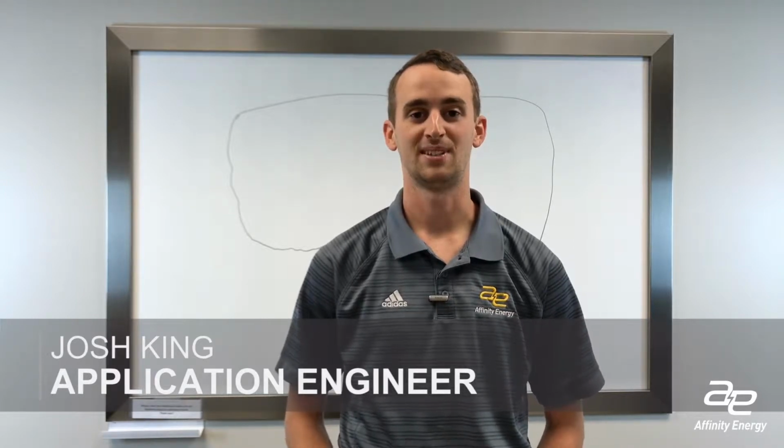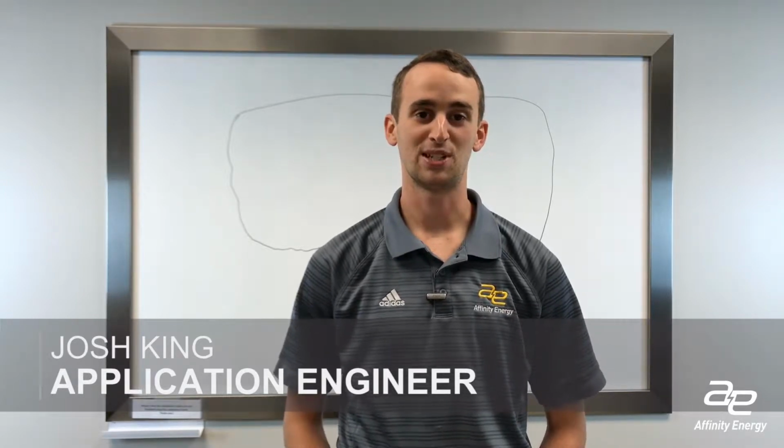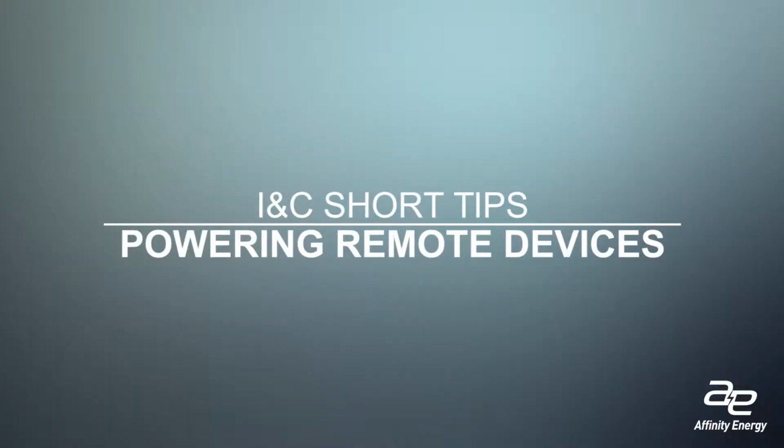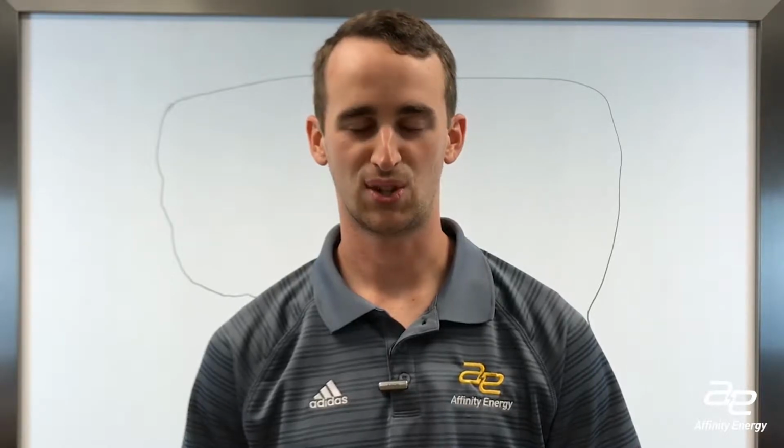I&C short tip. Specifically, we'll be talking about powering devices using solar modules and batteries. The three factors to consider when you are designing a system like this are the location, the power consumption of the devices, and the battery, the solar module, and charge controller.